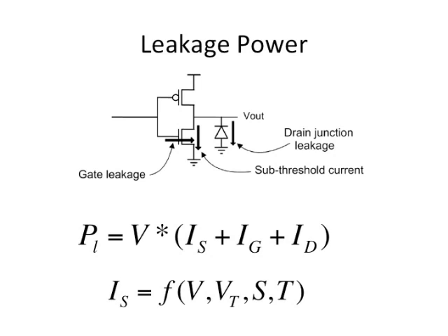So that's why the processes try to use a thicker gate oxide, but with a higher dielectric constant, to get you the same effect as having a very thin gate oxide, which is required for scaling of transistors. So basically the leakage is largely dominated by the sub-threshold leakage, which, if you recall from the previous class, depends on the supply voltage,